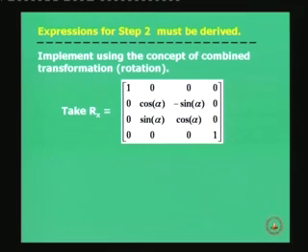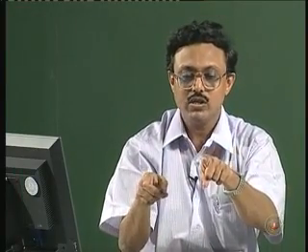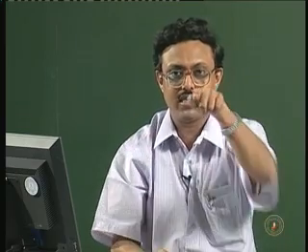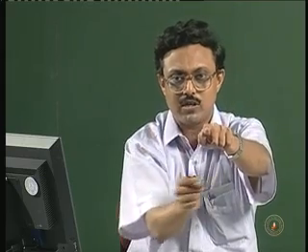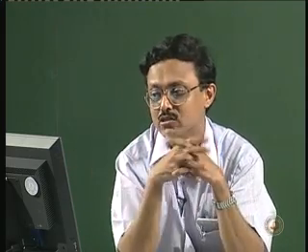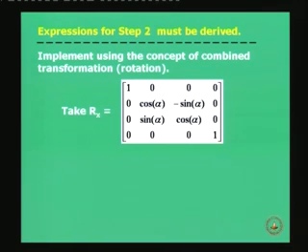a rotation matrix Rx. You know what this rotation matrix does? It takes a point in 3D space and rotates it about the x axis. So the x coordinate of that point will not be disturbed. Assume that the x axis is pointing towards you. You rotate about the x axis, so the x coordinate does not get disturbed, but the 2 other coordinates, y and z, change, and that is why you see the parameters cos alpha, sin alpha. Of course, we are looking into the axis with counterclockwise rotation, positive alpha, and the second and third axes will have the cosine alpha, sin alpha terms causing the change in the y and z coordinates. The x axis will not change.